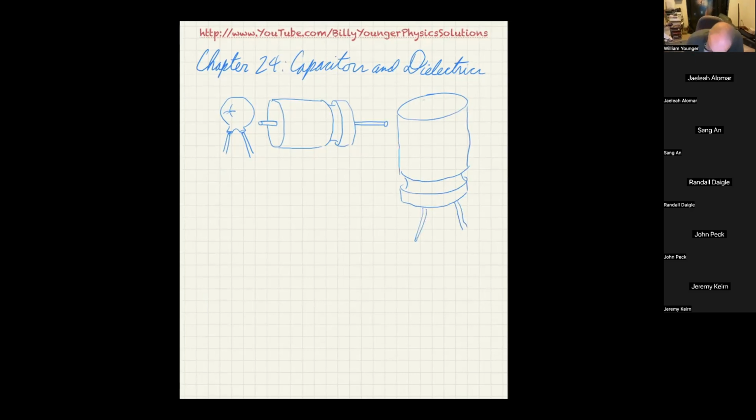A lot of times they'll have up here a nice little Mercedes symbol like that. What that does is, if this thing actually fails, a lot of times it'll get so hot and stuff will build up so high in there that it'll pop along those Mercedes lines and make a crack, and those little pieces will actually stand up. So as a technician, you would see, oh wow, this cap's been blown. I can see where the metal popped up.